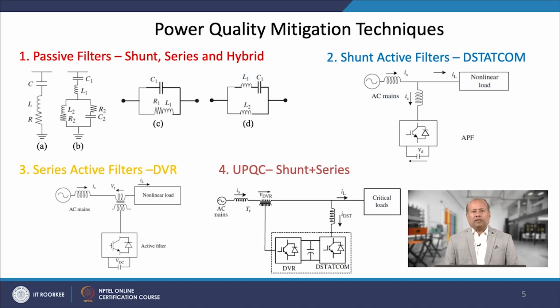The passive filters are extensively used in distribution systems for improving the voltage profile at the point of interconnection, power factor correction, reducing losses, neutral current compensation, load balancing and better utilization of electrical equipment. Ideally, the passive power filters can supply or absorb variable or fixed reactive power locally to compensate the power quality problem in the system.